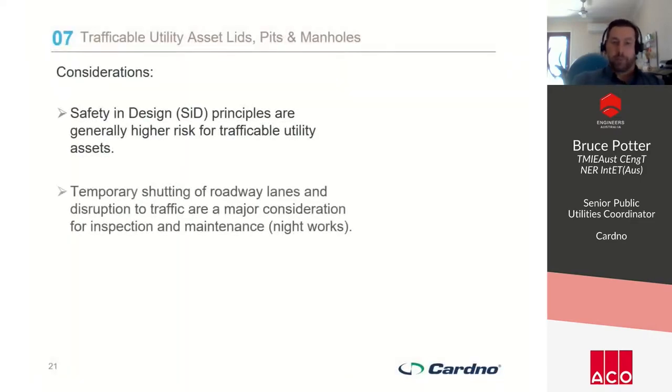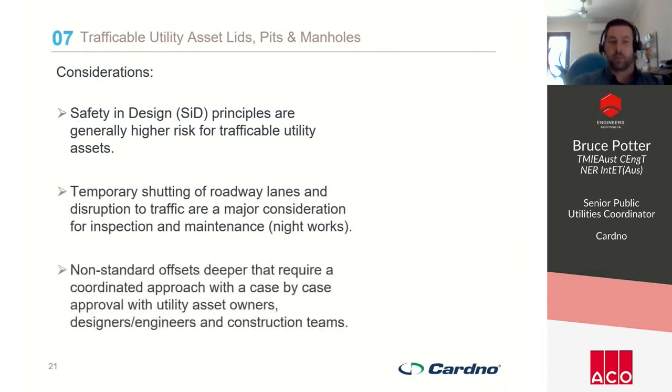So for considerations, from a safety design perspective, they are generally higher risk because they're in a trafficable area. When we're designing these assets, they need to consider the temporary shutting down of road lanes. So generally, these assets need to be put right in the middle of a laneway or off to one side of a laneway. This allows for a bit of consideration for the inspection and maintenance, mainly for night works. Again, if you're in a residential street, they could do this during the day. In a capital city CBD, most likely night works.